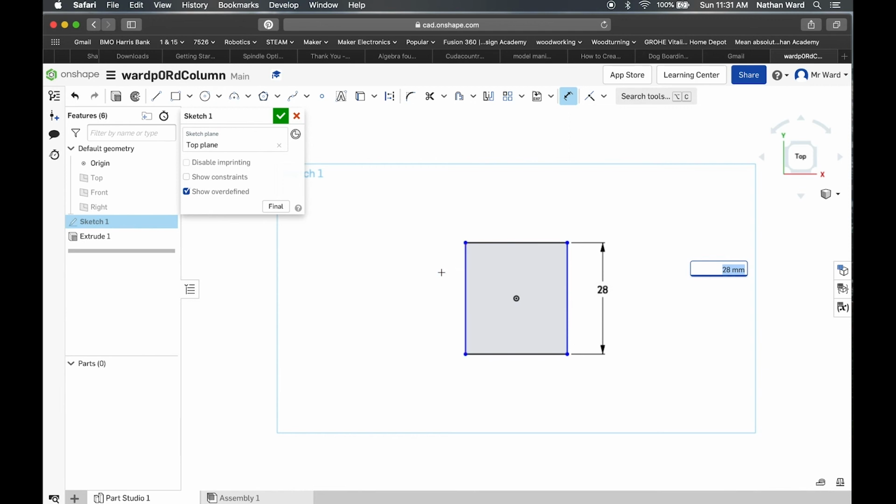I can pull this out. I have the dimension tool in my hand, so I can't really do it, but I could change the shape of this thing by dimensioning this line or by dragging it out. But these two lines relative to the origin point are always going to be 28 millimeters apart from each other. So that's why they're still lit up. If I go to either one of these other two lines and click on it, you're going to see the number that it already is. I'm going to change that to 28. And now because I'm done, I'm going to hit the return key.